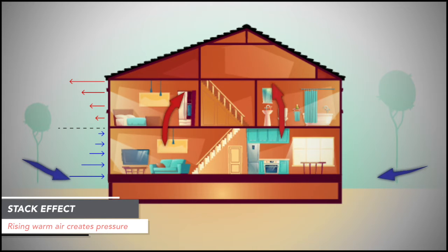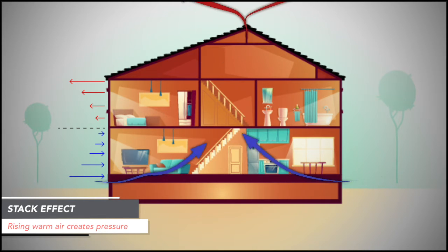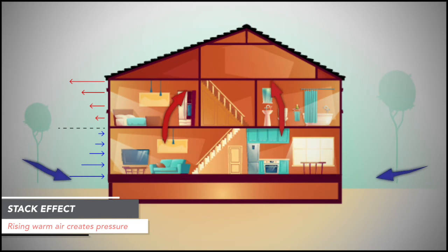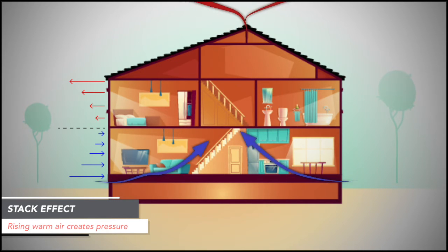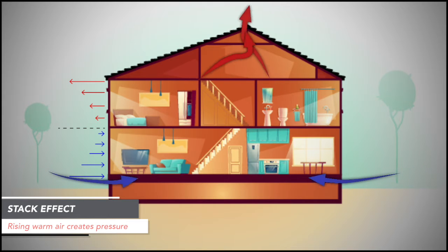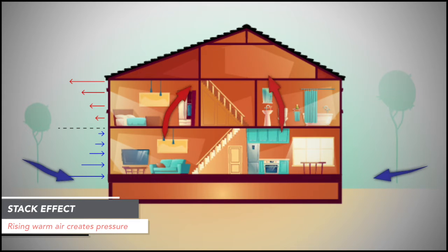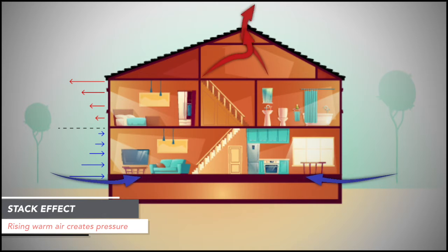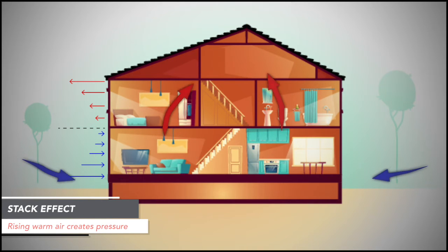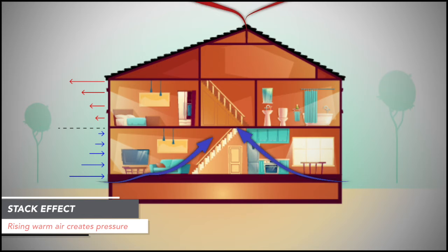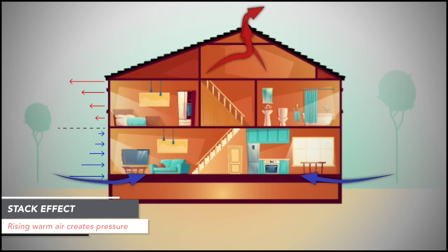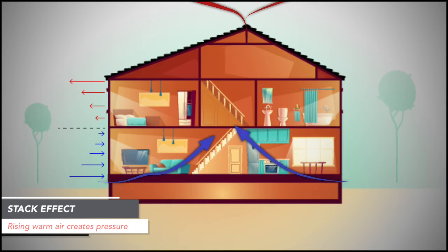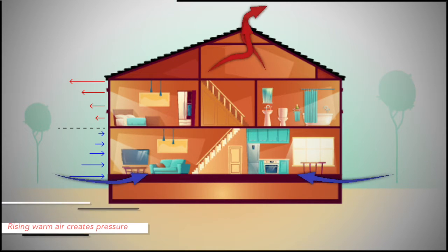As warm interior air rises, it develops outward pressure on the upper elements of the structure, while placing inward pressure on the lower elements. Regardless of exposure, climate, or design, this effect occurs 24/7 in all buildings. The upward movement and exfiltration of air up high results in unconditioned exterior air being sucked in at lower levels, mostly through the gaps, cracks, and openings at the foundation framing interface.